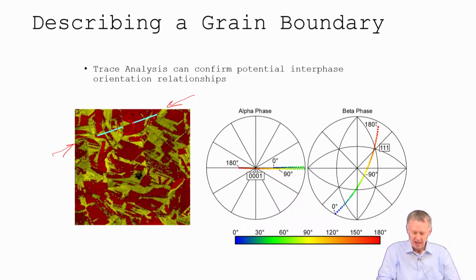So we have a trace that is consistent with it being a basal plane that forms along the grain boundary, but it could be any of these orientations along the grain boundary, right? So this is just what plane lies along the grain boundary. So it might be the basal plane because your hexagon's there and our line's there, but if you rotate it like this, it could be anything from a pyramidal plane up to a prismatic plane. It could be any of those. And so we don't know, but we know it's consistent. So if we expect to have a basal plane there for certain types, we could check it and say that's consistent with what a basal plane is.